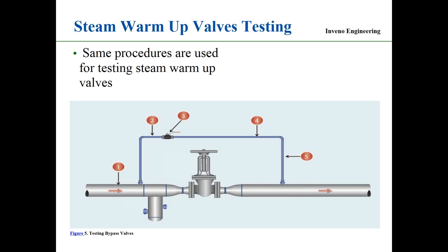So ultrasonic sound is very directional. By taking these points and seeing the increase at the discharge side of the valve, it tells us it's leaking. All ultrasonic levels should be pretty close. Nothing's going to be perfect. They're not going to be 25, 25, 25. Life's not perfect, okay? So as you see, the increase means there's ultrasonic sound being generated. And that's a quite common process that we use on warm-up valves all the time because we want to make sure that they are in the seated position. Specifically, if we go for a shutdown at the end of the year, we want to know all the valves that are leaking and get them corrected.